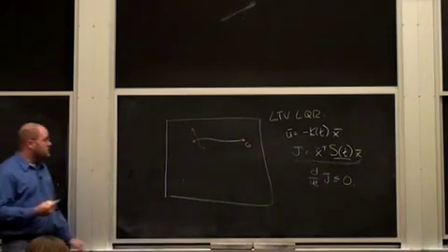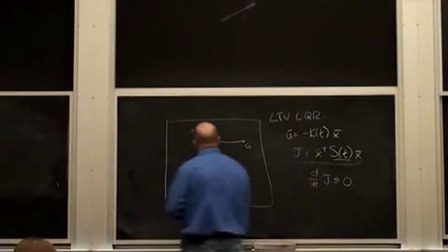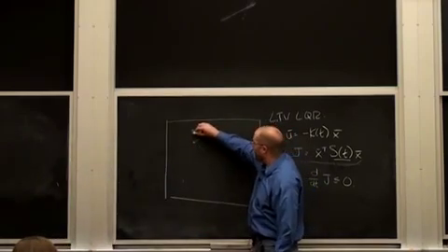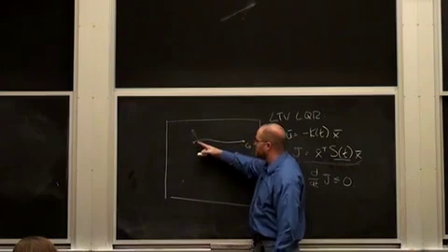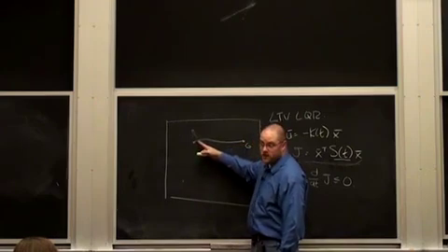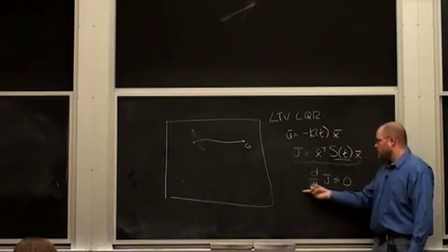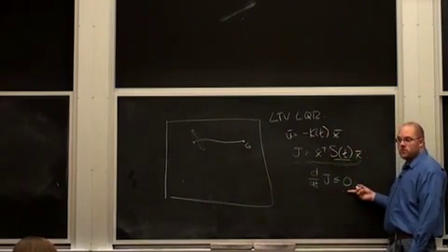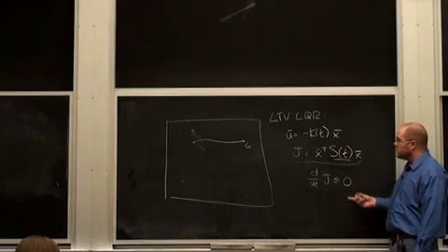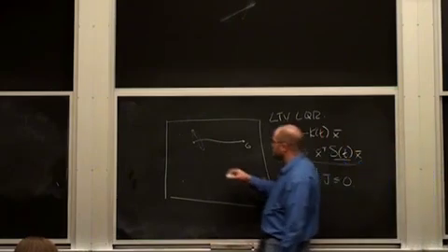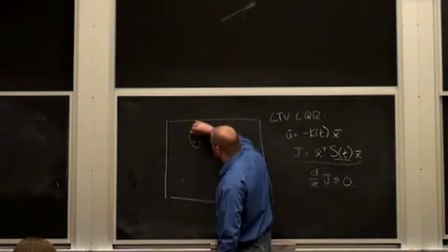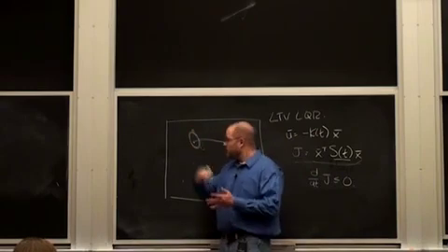So the idea with the certificates is to do a higher order polynomial expansion of the dynamics along this trajectory and try to estimate the threshold where this stops being true. Okay? And that gives me essentially a funnel.